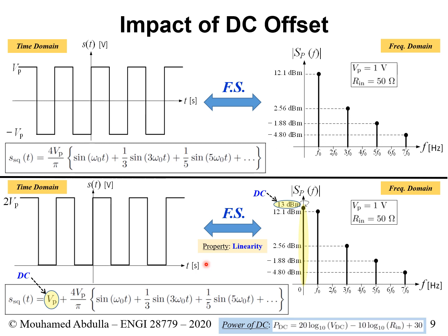The third approach essentially would be to look at your signal and detect whether you have a DC offset or not. You could look at your signal and ask, is my signal even? Is my signal odd? If your signal is even, then you may have a DC component, or you may not. It depends, right? Just because you have an even signal does not necessarily mean you have one. But at least you know for sure that either you have it or you don't.